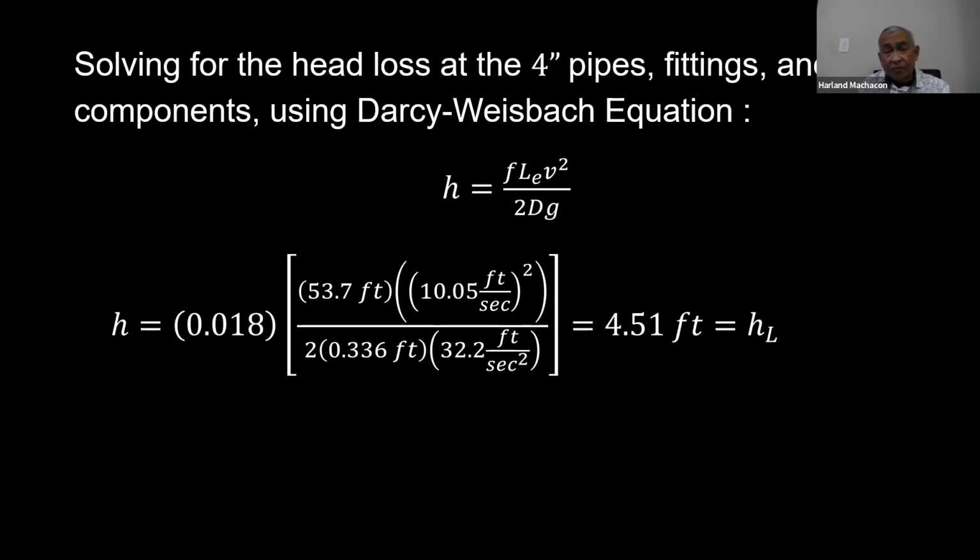And we can round off all these values to 0.02 without much error. What I do in actual practice, once I get the first Moody friction factor 0.021, I just round all these friction factors for the different sizes to 0.02, and you will save time. But anyway, the head loss for this run of pipe will be 4.51.